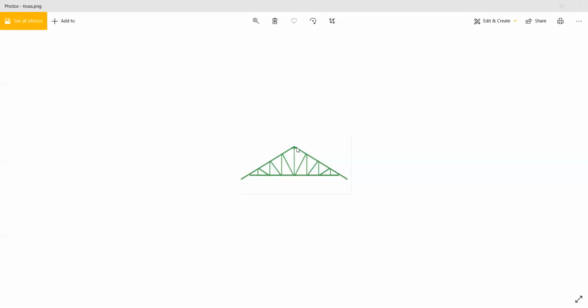Am I making sense to everybody? If we don't restrain the corners, and I'm emphasizing the word restrain, then we don't have any reaction forces, and we don't have any stresses in this truss. So when I say boundary conditions and applying restraints, that's what we're doing. We're restraining it in the Y direction. If we put reactions here and we apply a Y force here, that's what I mean when I say restraints or boundary conditions. That's what I'm talking about.